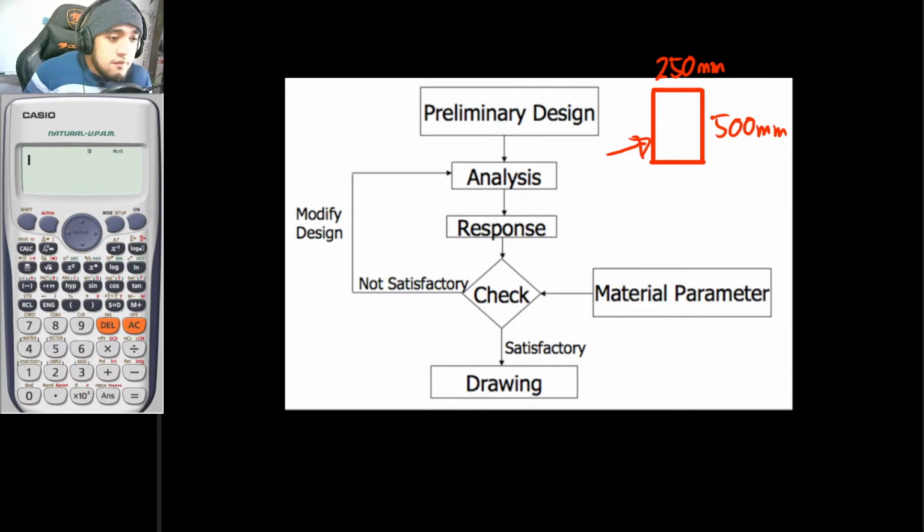Then after analysis, you will now be checking its response to the loads. So it is to be in this step wherein you will be knowing the deflection and its limits. So, ayun, meron tayong mga ibang parameters sa deflection na kailangan i-check kung pasok siya. So, okay. By the way, wait. Okay. So, after your response, so after checking if your member is to be adequate in, let's say, bending or let's say compression, then after which, you will now be checking its deflection. Then after which, once again, you will now be checking the section overall. So, i-check nyo kung pasok itong 250 by 500 natin, no? So, for example, that it is adequate already and it is to be economical, then you will be proceeding to the drawing part already.